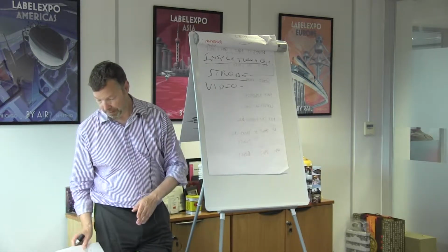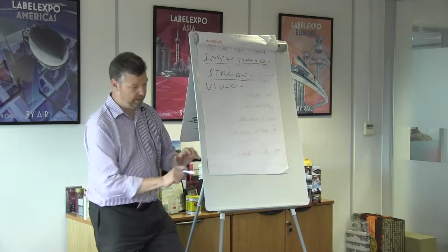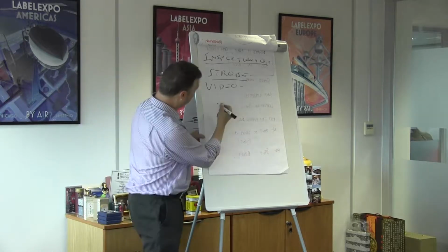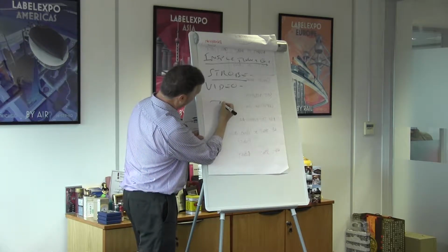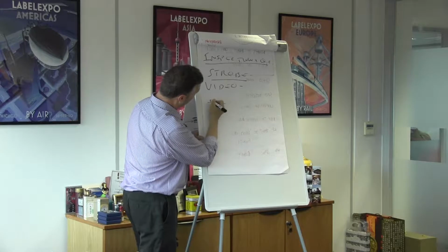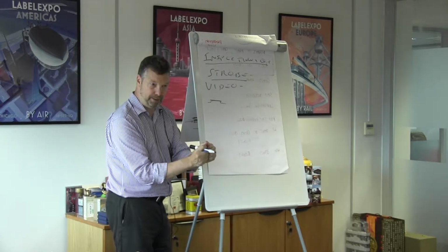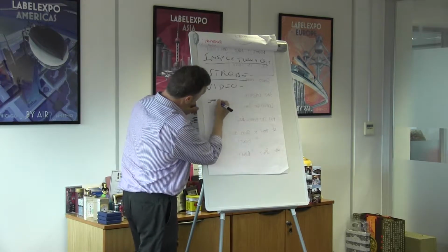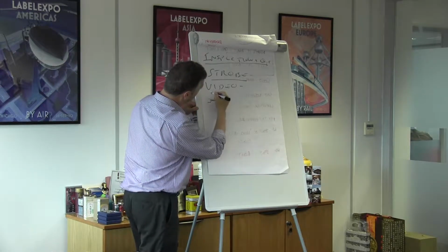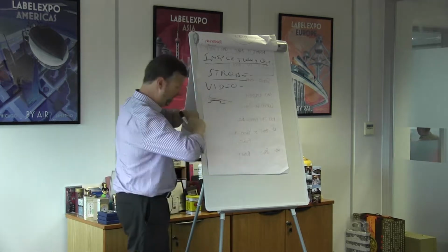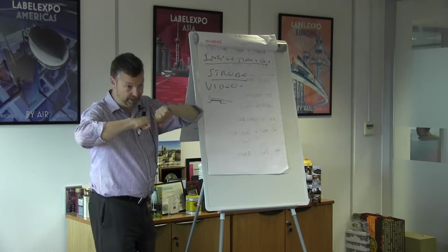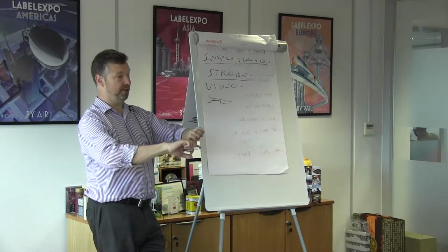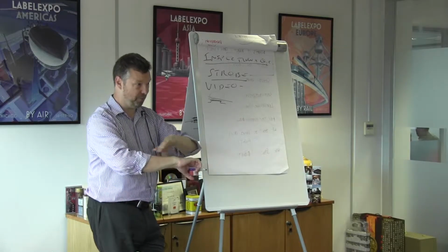And dot gain is where there's too much. Remember when we talked about flexography, and what we said was that it's like a soft dot with the ink on top of it. Remember that soft plate? If you press too hard against the material which is going through there, then you're going to get squashing. If you get squashing, you get too much ink, and then all the colour goes completely wrong. Instead of 30% cyan, you suddenly have 40% cyan, so the whole colour's gone wrong.